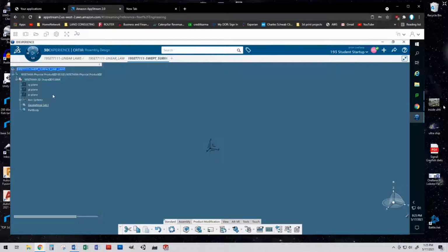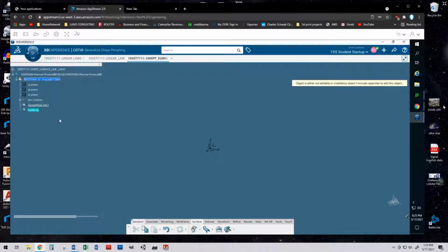And what I'd like you to do, please, is select the line command. I'm sorry, we're still in the assembly mode. Double click on the part body or the geometrical set. So we're fine, it's active. We're going to create a line.